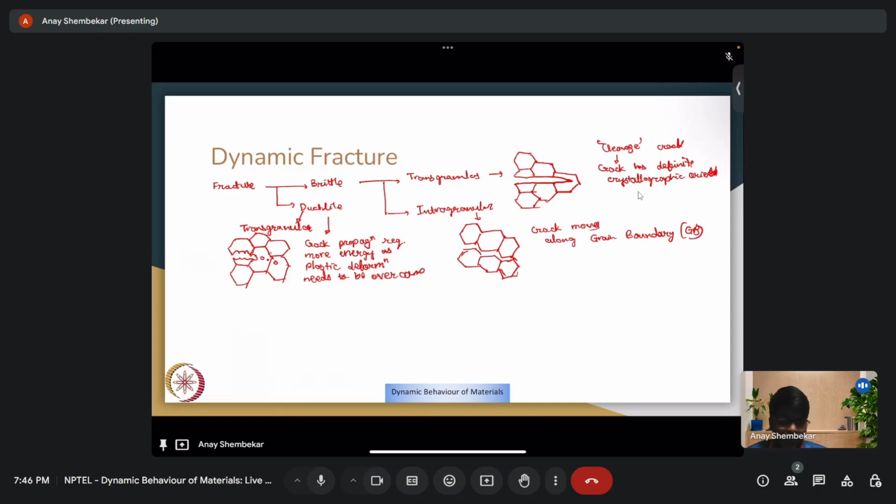One more important thing is that you see a crack tip blunting as the voids coalesce together, and you also see void coalescence leading to crack growth. So basically, these voids will join along the crack tip, which macroscopically would look like the crack is extending forward.